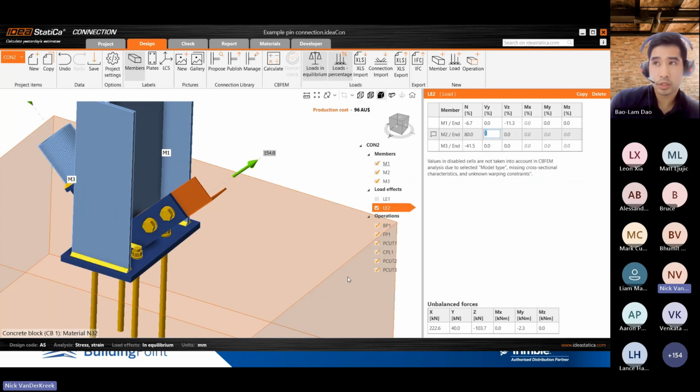But we have asked for minimum design actions to be automated. Now, it's a bit of complexity, so it depends on the type of connection. Is it going to be a simple type of connection, a compression connection, column splice, and this sort of thing? So the code gives different minimum values, percentages, or absolute values. So we might need some radio buttons or some options to tick that you want it to be this or that connection, and then set some minimums.